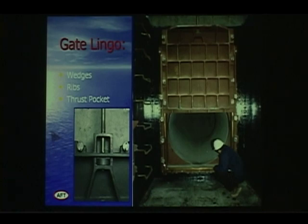Also here you can see your wedges. So you've got 4 wedges here. This bottom wedge here is on the frame. That's going to mate with this bottom wedge here. This second one here is going to mate with this one, and so on. And this is the top one, and that's the top one. So they're really only going to engage when the gate moves down to this position. They're only engaging for a short distance of the travel right at the end, at the fully closed position.